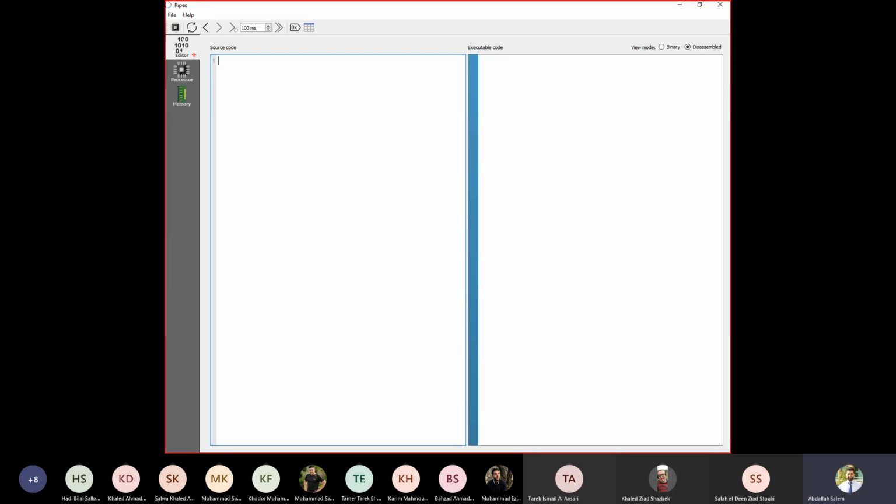In the editor tab, we show 2 segments. Here we have the left segment and the right segment. On the left segment, you can write your assembly program, which is written using the RISC-V RV32I instruction set. Whenever any edits are performed in this area and no syntax errors are found, the assembly code will automatically be assembled and inserted into the simulator.